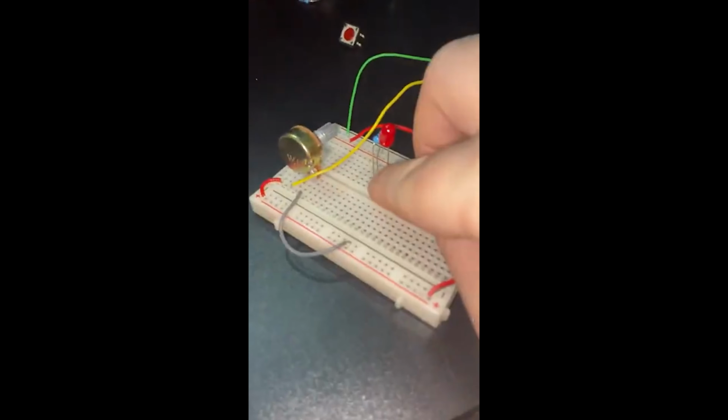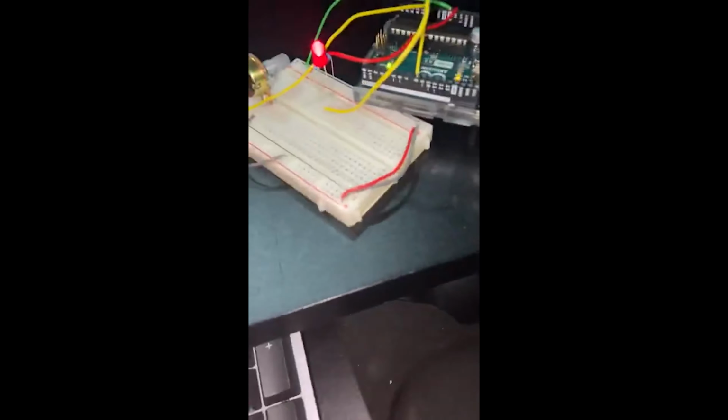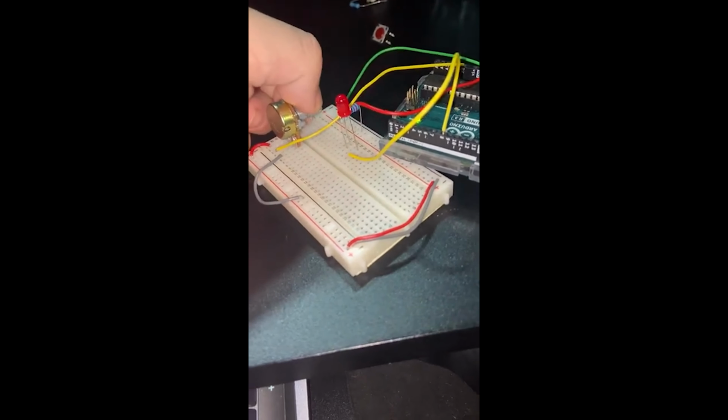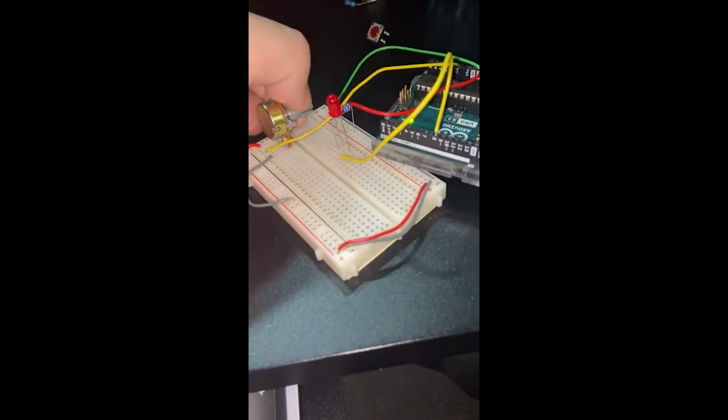Now, again, to see this visually, because we're just storing this value in a variable in the code, and we're using that to affect the delay, we can stick this into pin 8, because, again, that's what was in the code, and then connect that to the LED. Get that back in there. I bumped it, and we can see that now this is blinking, and as I turn it one way, that delay gets lower, so it blinks faster. As I turn it the other way, the delay increases, so it blinks slower. So you can decide what you want.